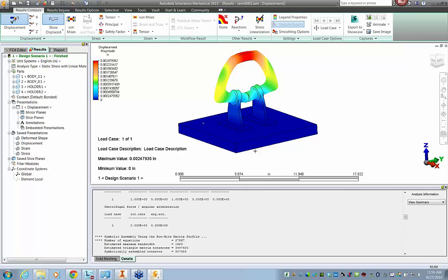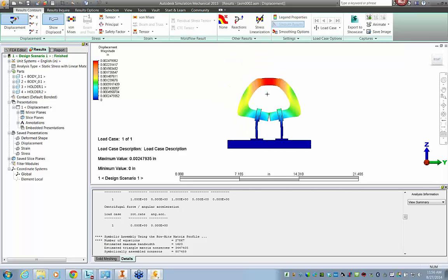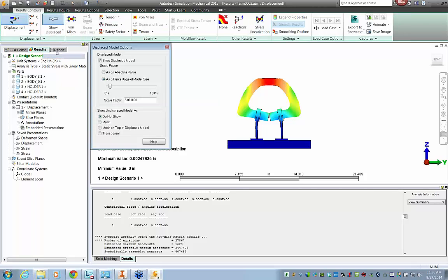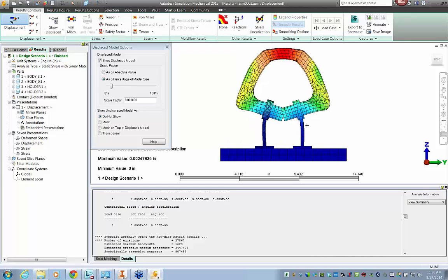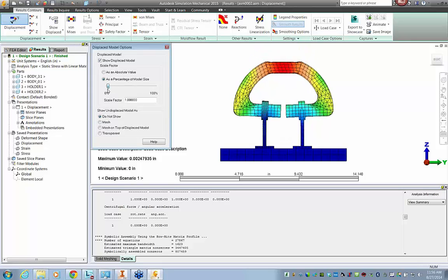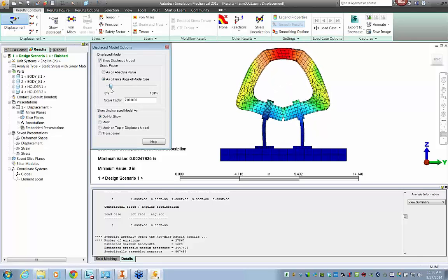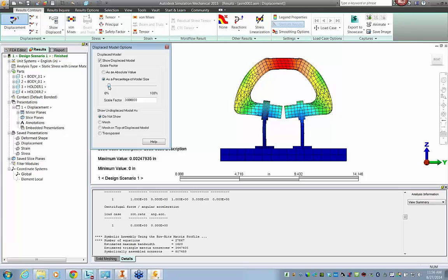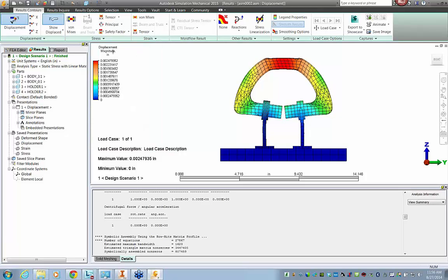And before I could even show you those, the results are displayed, and you can play with the displacement exaggeration and see that for the object that has the good mesh versus the bad mesh, the results are very symmetric, that you're not seeing anything out of the norm. The deformations are symmetrical because the load is symmetrical, the contact is being honored, things are not flying off in space, which is why we have our displacement result as the first result that we show as the default result type. So you make sure that it is actually small displacement because this is static stress, and then you can look at things like